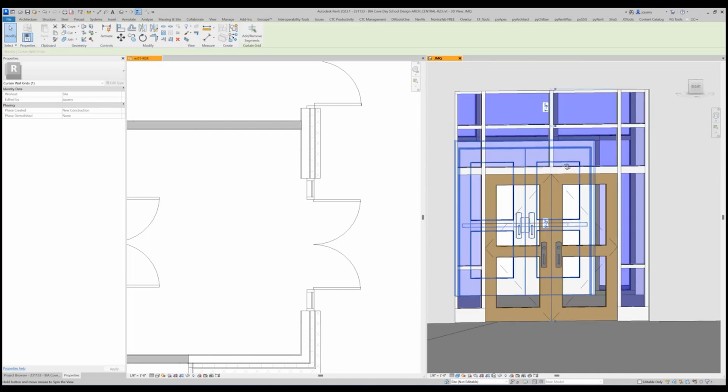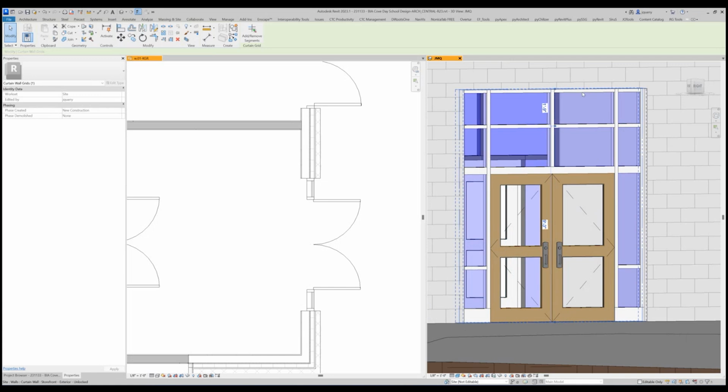But the massing is different. It shows that this one is supposed to be shorter than this one, and it needs to be the other option. So if 9'3", the next one would be 8'8", so this would be 8'7", right? So now it aligns with this coursing, and you get the massings close. It's not going to be exact because we've got an extra 2 inches of mullion. Does that make sense, Marcus?